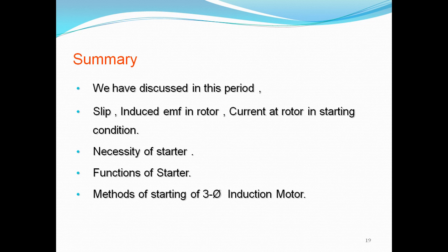When the motor reaches its normal speed, then we disconnect the external resistance from the motor. So likewise, the rotor resistance starter is going to work.